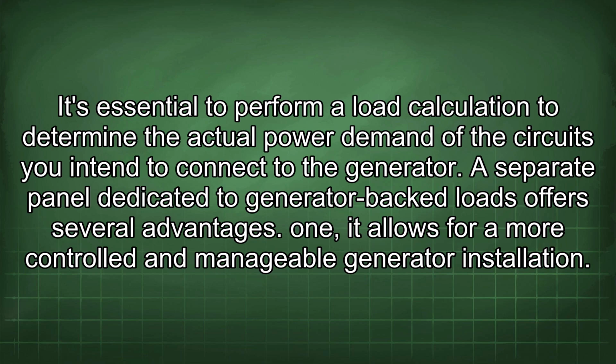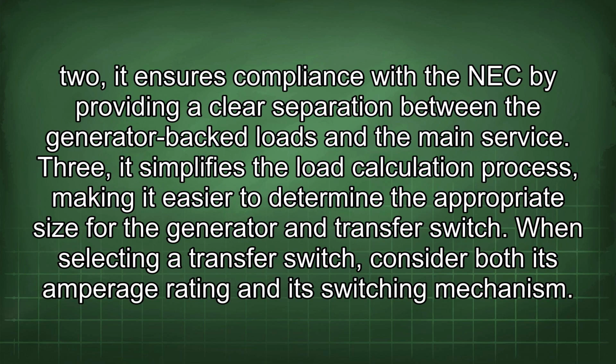1. It allows for a more controlled and manageable generator installation. 2. It ensures compliance with the NEC by providing a clear separation between the generator-backed loads and the main service. 3. It simplifies the load calculation process, making it easier to determine the appropriate size for the generator and transfer switch. When selecting a transfer switch, consider both its amperage rating and its switching mechanism.